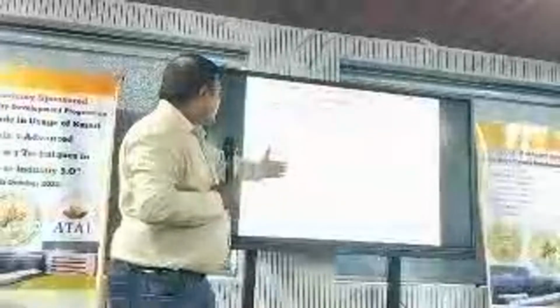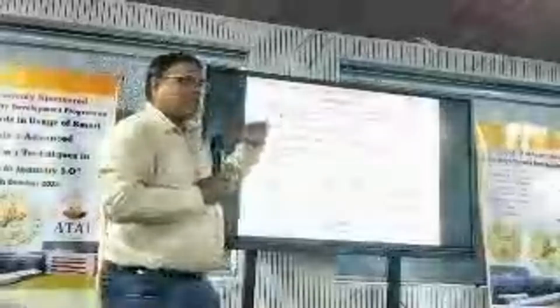Like what I explained. First you have to collect the mass of the machinery and the speed in RPM of the machine, and calculate the disturbance frequency, RPM by 60. Then you can find the load on each mount and the natural frequency of the total system. And if FD by Fn is greater than root 2, that is the isolation zone, then only you can go ahead.